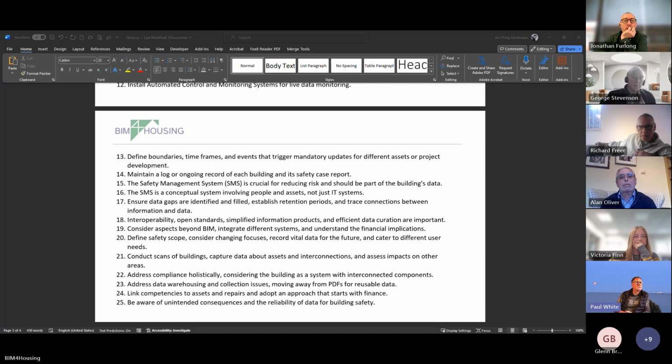The other thing is that if you think fire doors are bad, you haven't even thought about doing your fire dampers yet, because I bet I can go into any of the buildings that any of you are related to, and they've got fire dampers in, that there's a high proportion of those that weren't installed properly, and it will be obvious. And when you have your next fire damper inspection, that people are doing it more competently now, rather than just checking that they open and close, you're potentially going to have a completely different issue there.